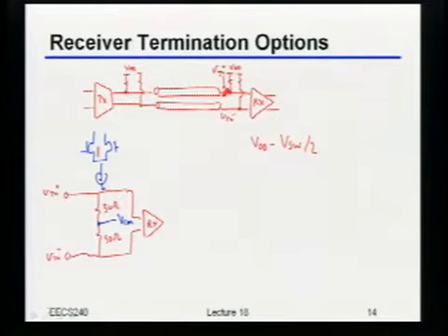Okay, so this was a nice idea, because it almost looked like I could set the common mode to the receiver. So I claim actually this is not so bad. We just have to make one additional modification, which is a little bit of cheating, but AC couple. Yeah, there we go. You just have to AC couple, right? So let's actually go and draw that other option. So if instead of doing directly what was drawn there, I just add 2 AC coupling caps.